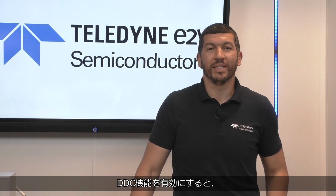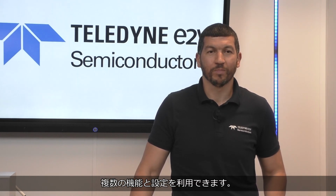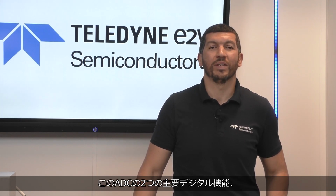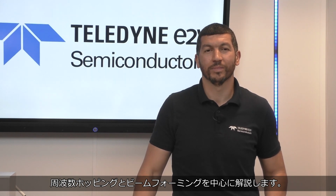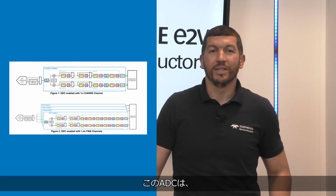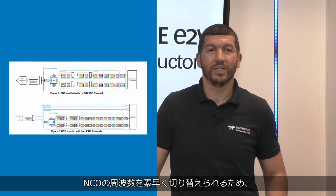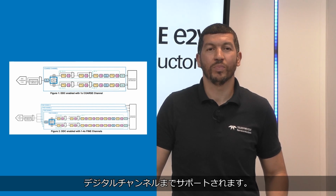When the DDC is enabled, several features and configurations are available. In this video, we will focus on two main digital features of this ADC, the frequency hopping and the beamforming. This ADC has the capability to quickly switch the NCO frequency, and thus the frequency band of interest is supported, up to 4 digital channels.